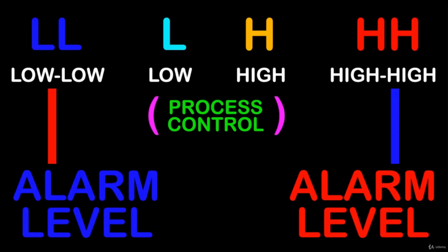When we look at our PLC, it's showing us a bit associated with the output that says, yes, the heater is on. The problem is, like any real-world appliance, sometimes they break, and when you turn it on, nothing happens. And how are we going to know that?